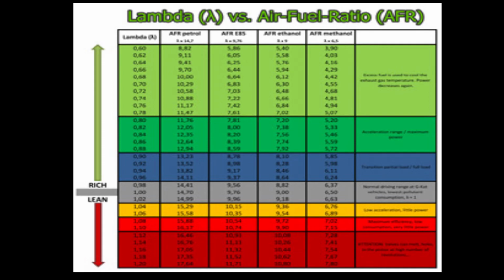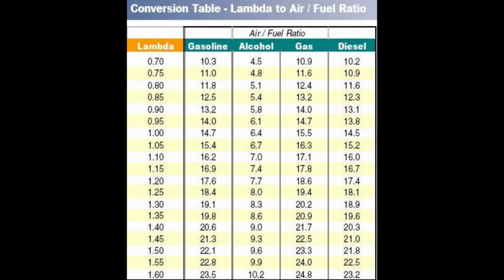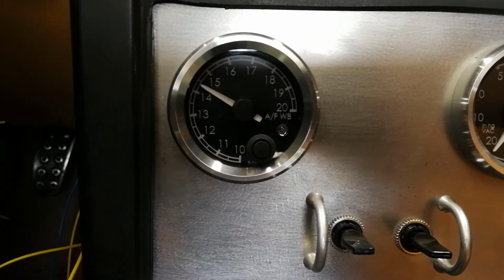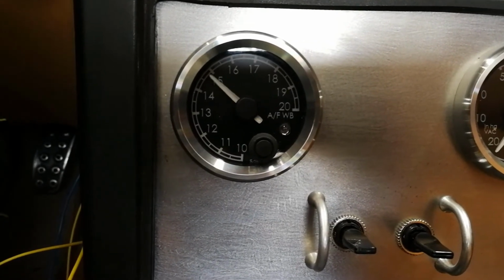There are a couple places that E85 may give more power at slightly leaner AFR, and we'll get to that. But you'd have to adjust this regardless of whether you're using gas AFRs, ethanol AFRs, or Lambda. The AFRs are just a display. So for now, don't change anything.